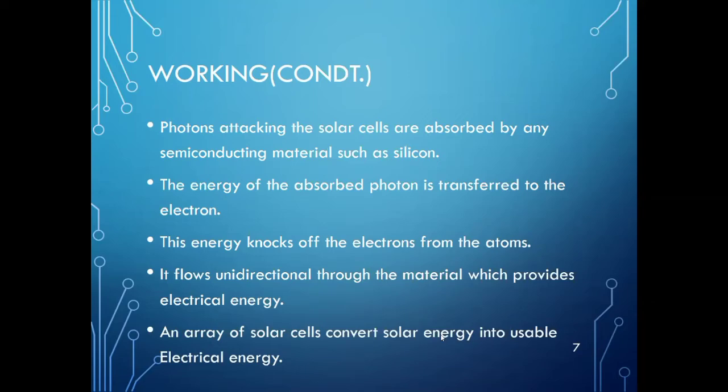This all adds up to an electric field at the junction between the silicon layers. And when a photon of sunlight knocks an electron, the field will push that electron out of the silicon junction. A couple of other components of the cell turn this into usable power. Metal conductive plates on the sides of the cell collect the electrons and transfer them to the wires. And at that point, electrons can flow like any other source of electricity.